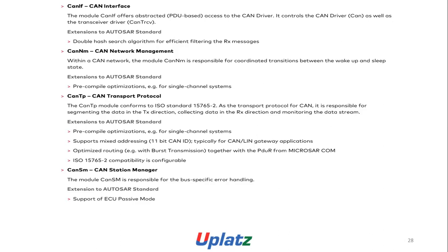CAN NM, CAN network management. Within a CAN network, the module CAN NM is responsible for the coordinated transition between the wake up and sleep state. Extension to the AUTOSAR standard: pre-compile optimization.